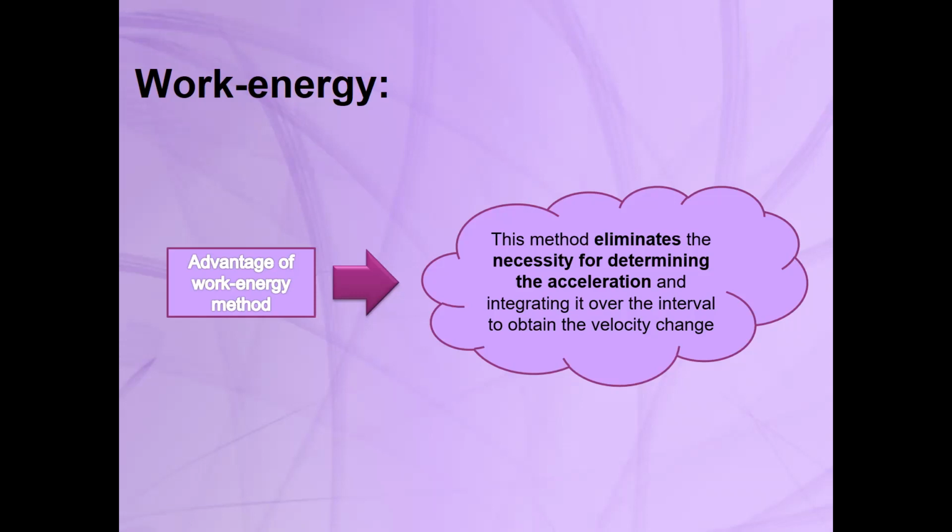And then you can integrate over your interval to obtain the velocities. So we don't need to find the acceleration to obtain the velocities and displacement, and finally to obtain the reaction force. You can easily find the reactions and the forces using these work and energy equations. The procedure is exactly similar to the particles. There is no difference here.